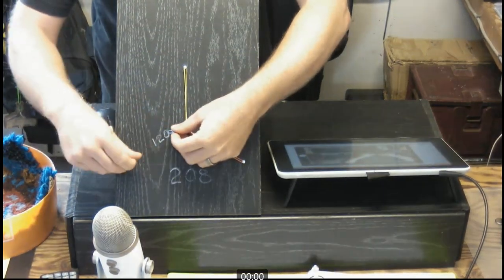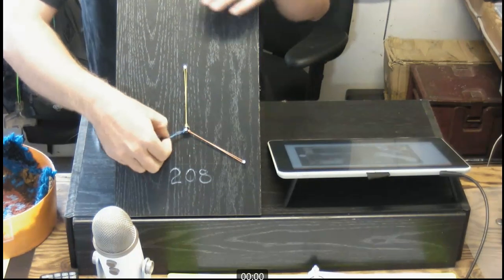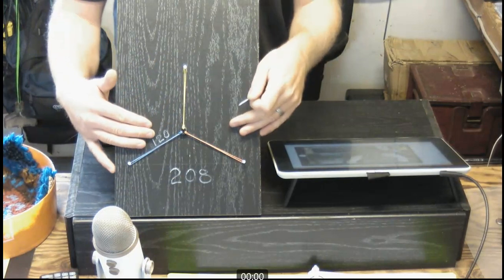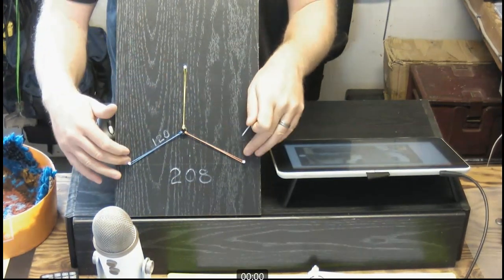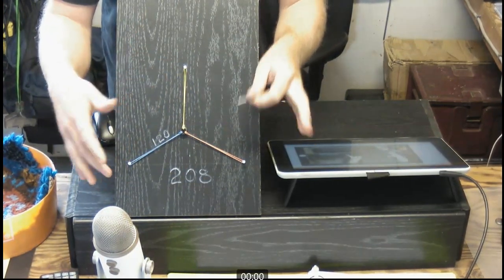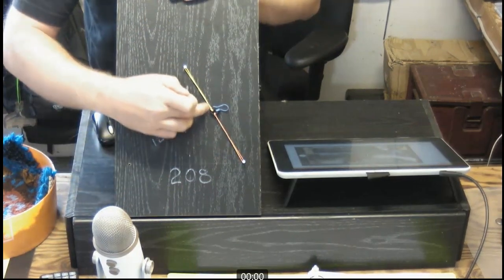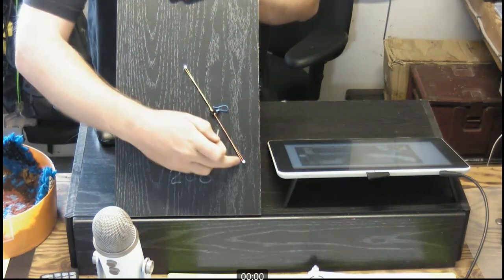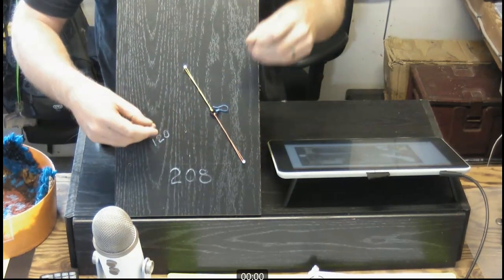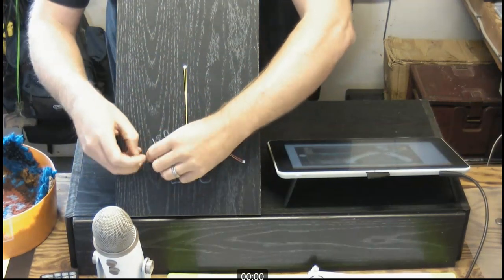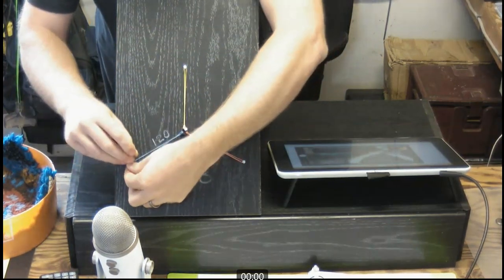Let's just try it one more time without the neutral inside there. If we don't have a neutral, I'm just going to pull the neutral out. If we don't have a neutral and all three of my lines or loads are good, we're fine. But if I don't have a neutral and I lose a line, we see that the voltages across these change, right? They get smaller. They're no longer going to be that full 120 volts that we would have across it.